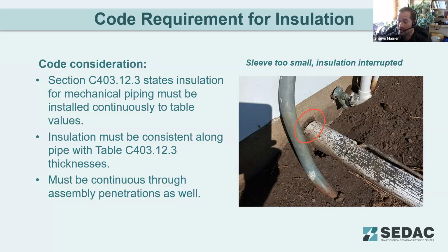The other possibility we see in some buildings is where you have firewall partitions made of drywall or something like that. If you butt insulation up to that drywall but don't pass it through, and you develop condensation there, say it's a chilled water pipe, now you've got damage not only to the pipe from condensation, but it can also get onto that drywall, and now you've got mold and mildew issues on that drywall penetration. So there are some considerations here for why this insulation matters beyond the energy performance; there are other maintenance considerations as well.